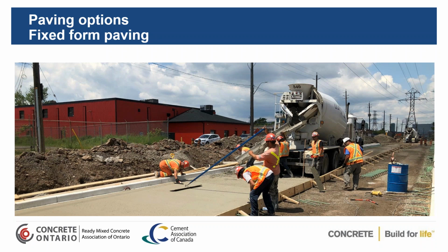One key thing, if you're using wood, you have to use a form release agent on the wood to ensure that when you take that form off, it doesn't have a bunch of the paste bonded to it, and you pull it away, and then you get some honeycombing type look on your concrete pavement. And I'll actually show you a picture of that shortly.